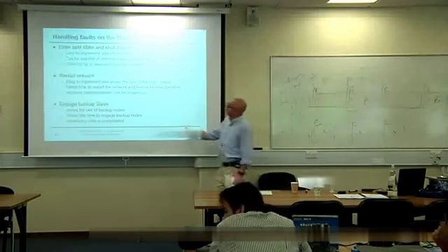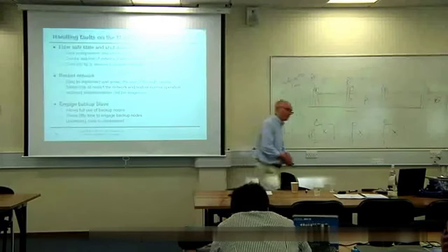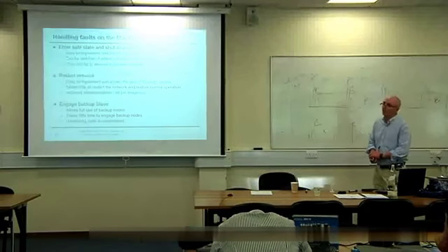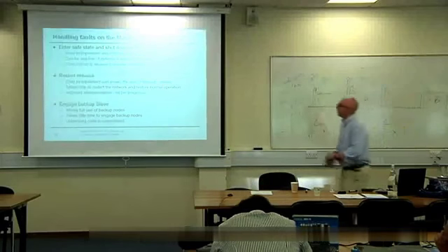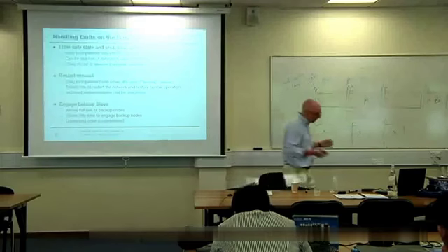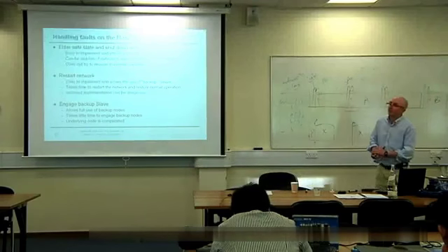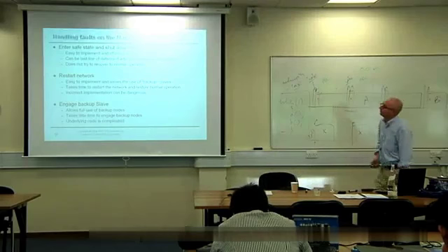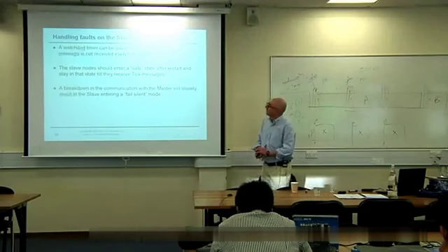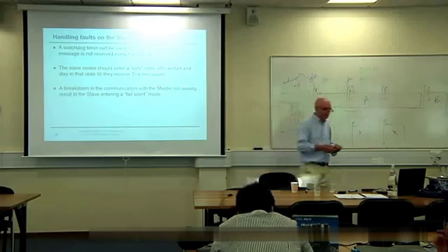We might need to restart the network. We might decide to restart the network and just assume it was a temporary failure and run from there. Or we can engage backup slaves or engage backup masters. There are various other possible combinations that we can run through. I think I've said this about use of watchdog timers to do this.